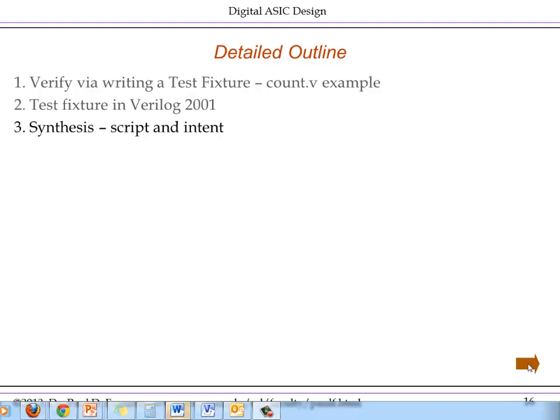they are doing. The synthesis script is as much of your design as the RTL, primarily because it specifies the timing and the timing interfaces to your design. And in addition, it specifies the strategy you want synthesis to use in order to optimize your design. We're going to mainly deal with timing issues here because they're the ones ubiquitous to all designs.